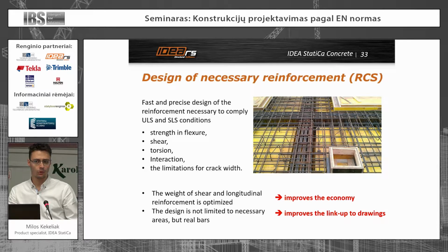As well, the RCS module, or the model implementing the concrete module, provides fast and precise design according to Eurocode. So there is automatic design of reinforcement that satisfies the ultimate limit state condition and as well the serviceability limit state condition.